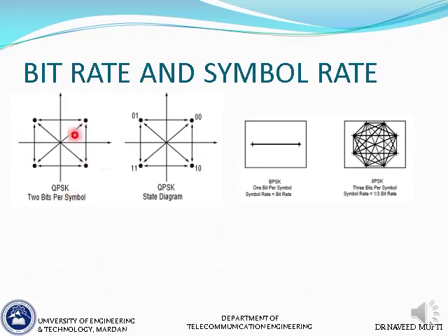तो लेट्स से अगर हमारे पास QPSK के we have 4 points on the constellation diagram, 4 constellation points हैं, and as we discussed previously, these 4 constellation points, basically every point represents a unique combination of 2 bits, as you can see here in this example. So every symbol basically represents, और every symbol can transmit 2 bits.